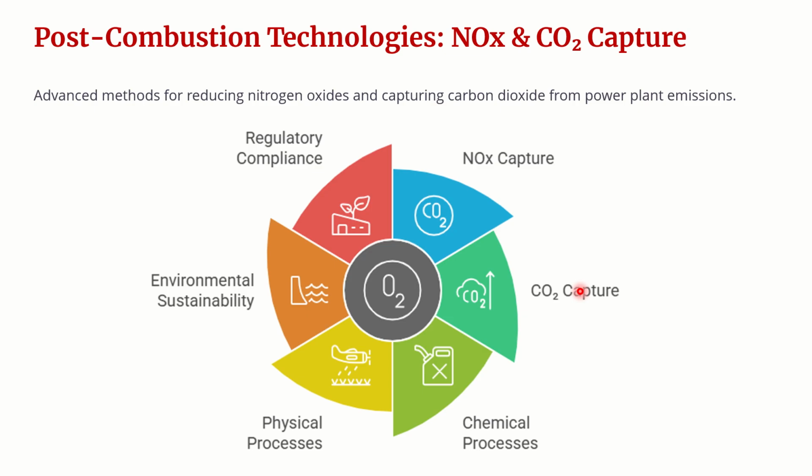The other one, calcium looping, which utilizes calcium oxide as a sorbent that reacts with carbon dioxide at high temperatures. The resulting calcium carbonate is then calcined to regenerate calcium oxide and release a concentrated carbon dioxide stream.